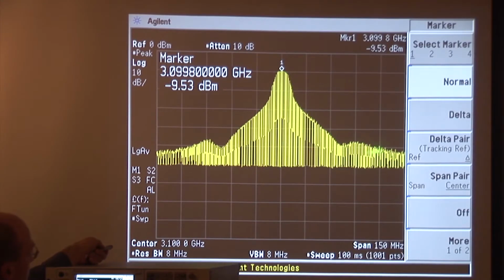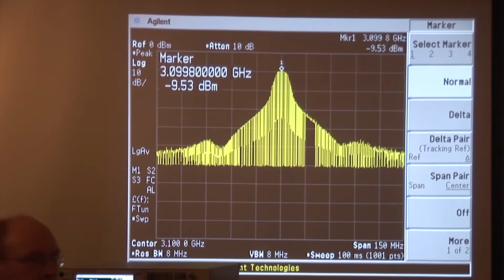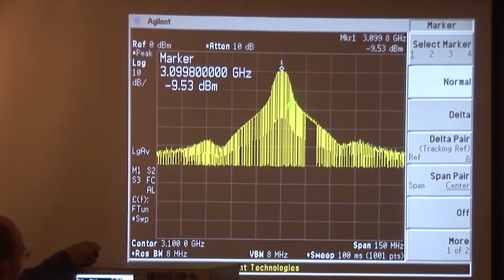So the actual absolute power contribution that we're getting out here in the out-of-band and the spurious parts of the radar emission spectrum is negligible compared to the power at the fundamental, which makes sense because when you're operating a radar, you want almost all your power to be on the radar's fundamental. There, we finally got it to fill in the way we want the whole spectrum to look like. But this takes a long time. Now imagine that instead of a radar looking at you every second, this radar is coming around looking at us every 10 or 12 seconds, or there's a weather radar that has a 1 minute rotation time. You can see how long this could take for a typical radar. So this addresses the low probability of intercept problem for radar emissions.